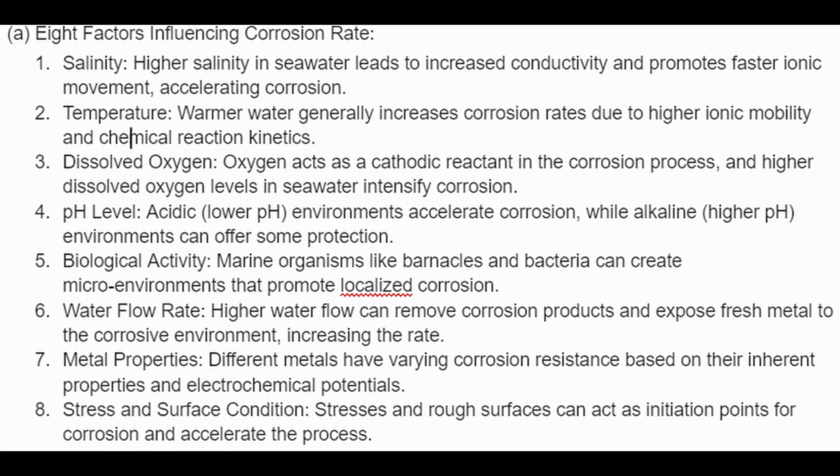5. Biological activity. Marine organisms like barnacles and bacteria can create microenvironments that promote localized corrosion. 6. Water flow rate. Higher water flow can remove corrosion products and expose fresh metal to the corrosive environment, increasing the rate. 7. Metal properties.